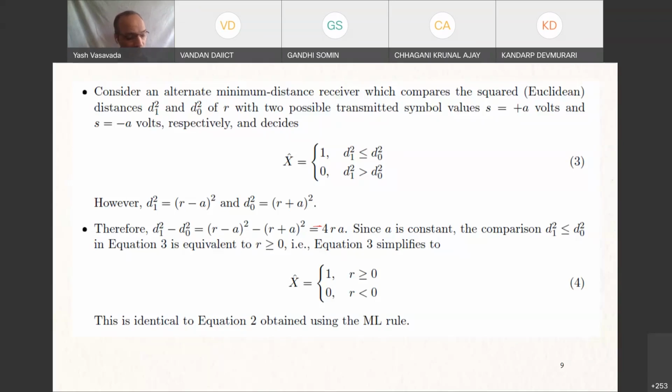Okay, so what I was trying to say is that from the perspective of estimation theory, a lot of the times the detailed mathematics of the Bayesian detection scheme boils down to doing just the minimum distance detection. And the minimum distance rule, we saw here, is mathematically completely equivalent to the Bayesian rule when the noise is Gaussian.